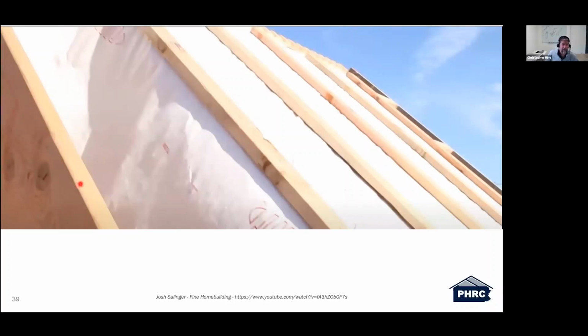Over here on the left-hand side, that's our 2x12 rafter. This is a high perm, very high perm barrier. I believe this product that they are using in this YouTube video actually is a commercial grade house wrap with, again, a very high perm rating, and that's installed directly over top of the 2x12. And then as you can see here, our 2x4s are nailed on top of that. That is creating a 1.5 inch deep air chase completely up through to vent this ceiling assembly.